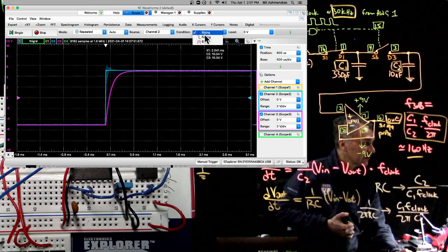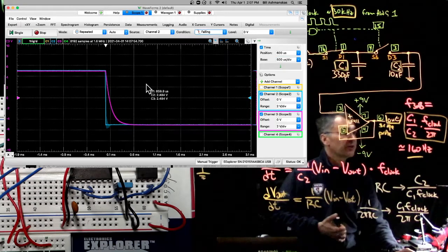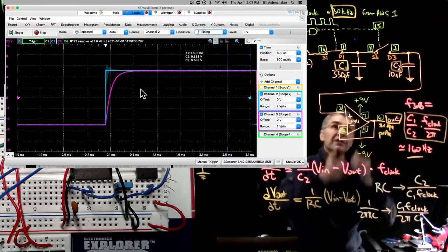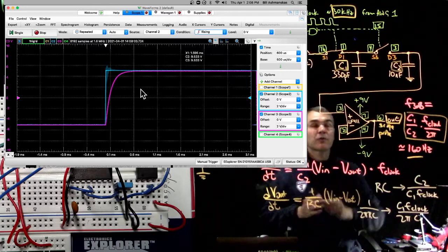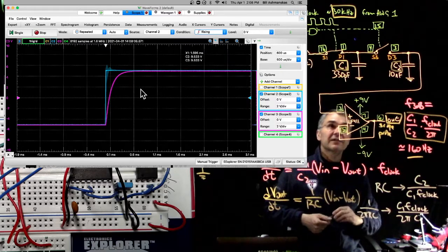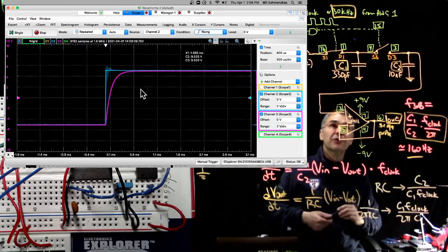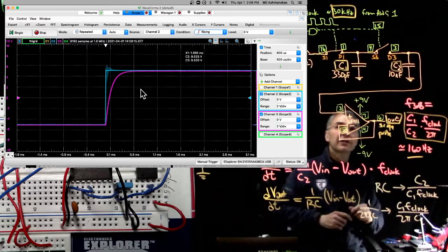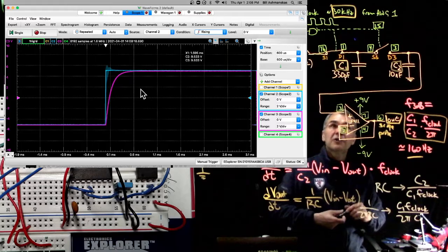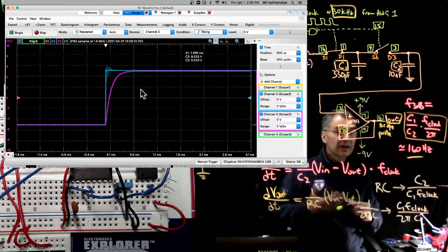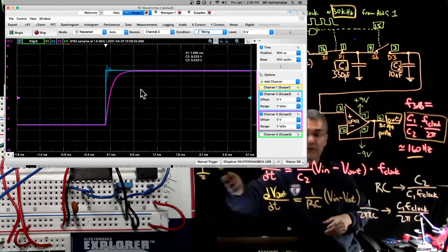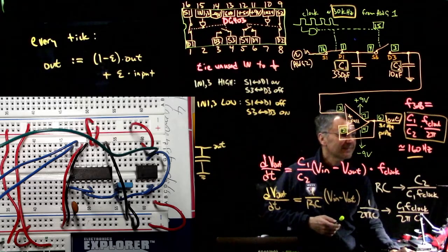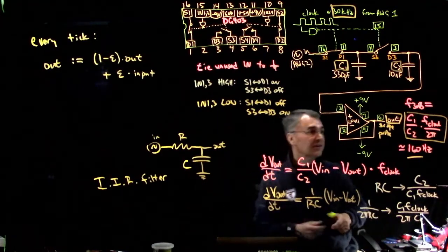And let me trigger on the other edge. Then you see the classic RC falling curve. So it's kind of neat. With switching back and forth and 2 capacitors that are quite different from one another in size, about a factor of 30, so this is like 1/3 of a nanofarad, and this is 10 nanofarads, we get the same behavior as an RC integrator.